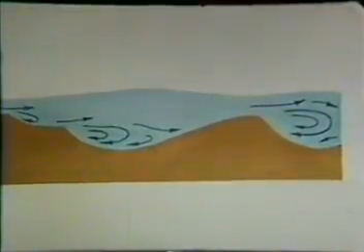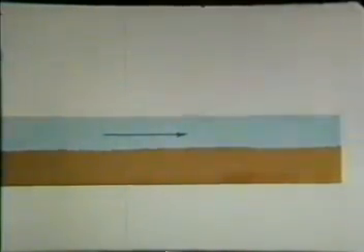In the laboratory flume, holding depth of flow constant and increasing the energy slope progressively, the following bed forms will occur: plain bed without movement of sediment, ripples, ripples on dunes, dunes, transition zone, where the bed roughness can be anything from dunes to a plain bed with movement of sediment, standing sand waves, anti-dunes, and violent anti-dunes.